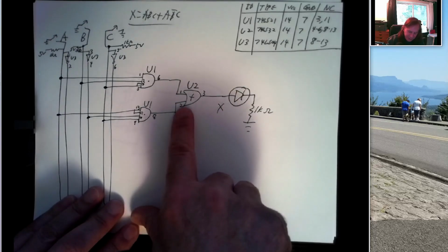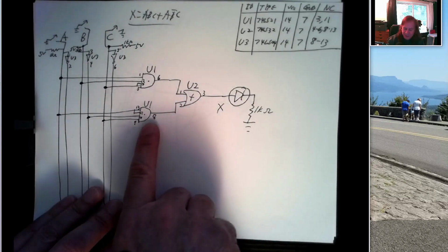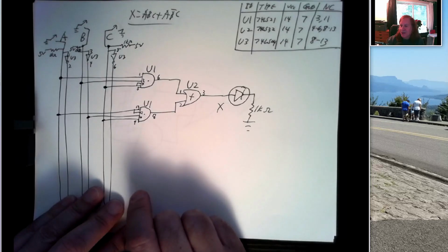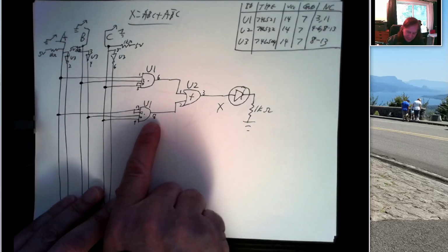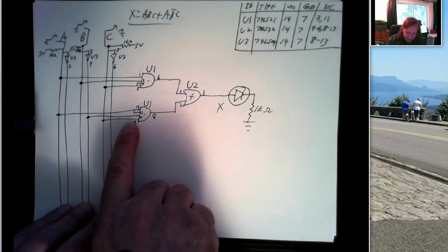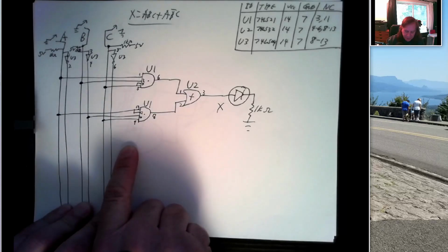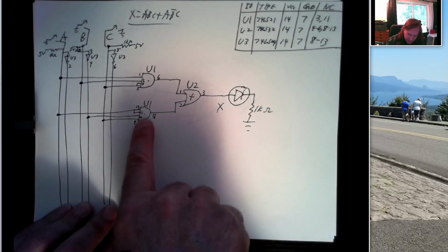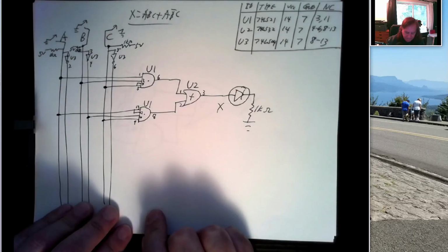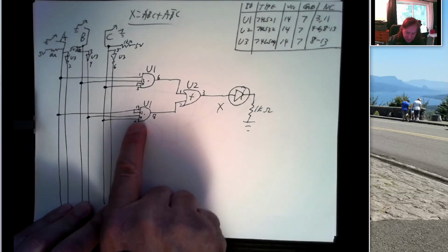If we're getting a 0 volts at pin 2 and we're getting a 1 here, it's a bad wire. Or maybe the wire's in the wrong place. But if we're getting a 0 out on pin 8, then there must be at least one of these inputs which is also 0. So now we take voltage readings on pins 9, 10, 12, and 13. And let's say pin 10 is low instead of high.